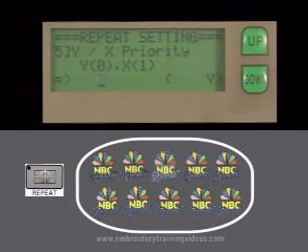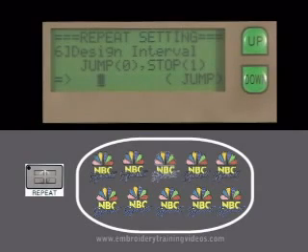Now the machine is looking for the YX priority. Is it a priority for the machine to sew in the left-right direction first or the top and bottom direction? If you're sewing on backing material, it's stable in both directions, so therefore this is not a very important function. For this particular example, I'm going to have it sew in the X direction first, so I would use a value of 1, which I press on the numeric keypad, number 1, then press the set key to lock in that value.